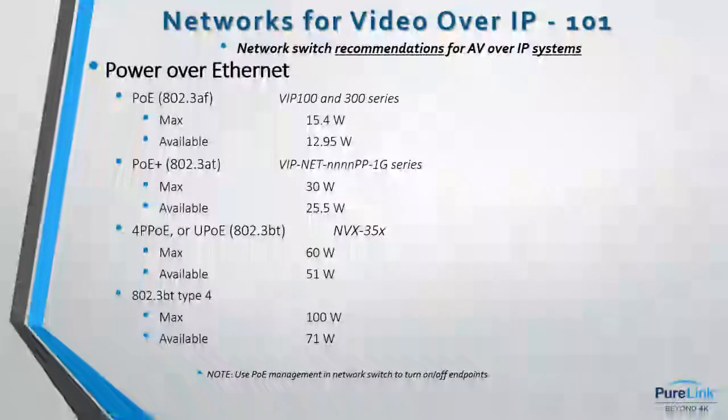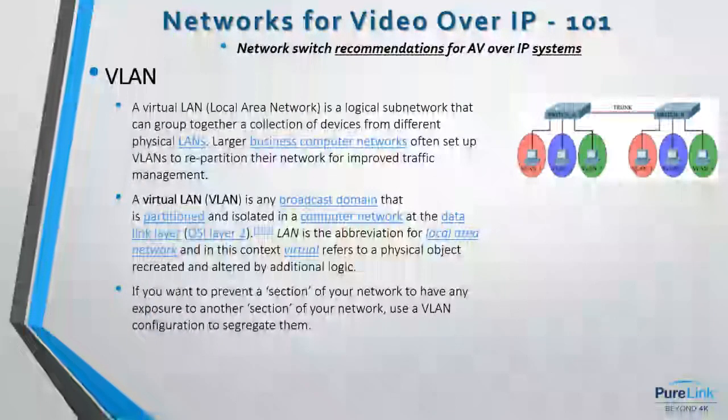So they're drawing almost 7 times what our product draws, which means they're generating 7 times the heat per device. They also have electromechanical fans in them. We don't. So these are all things you want to think about in the design, not just getting something up and running, but how am I going to deal with that thermal load, and what am I going to do if a fan fails, and lots of other stuff.